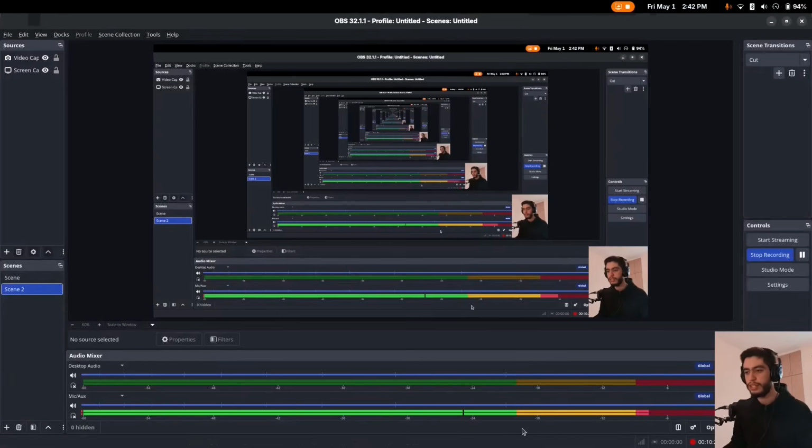On your old analog mixer, you might have master meters with negative values and 0 and positive values. And the middle where the green meets the yellow, that's the nominal level. That is the same thing as -18 in the digital mixers. So on old gear, it might seem like 0 is in the middle and it's not too loud, not too quiet. And on your digital mixer, you see -18 is like above 3/4 of the way up, and you're like, oh, that's too loud, let's turn it down. No, it's the same exact level. So I usually say where the green meets the yellow, that's the nominal level.